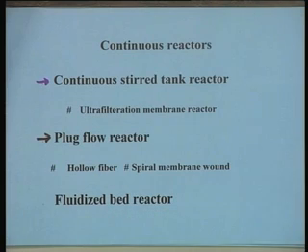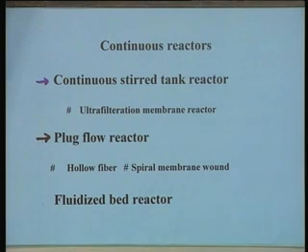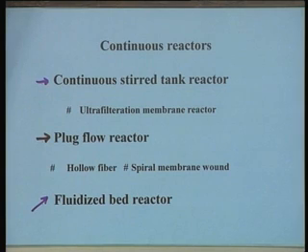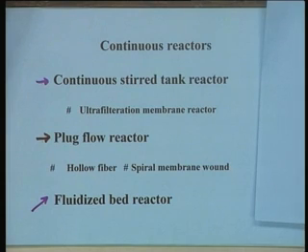The third category of continuous reactors is the fluidized bed reactor. They are essentially somewhere in between the continuous stirred tank reactor and the plug flow reactor. Basically, you put the substrate feed in at a speed high enough to lift the bed, or fluidize the bed, but not allow the catalyst particles to go out of the reactor.